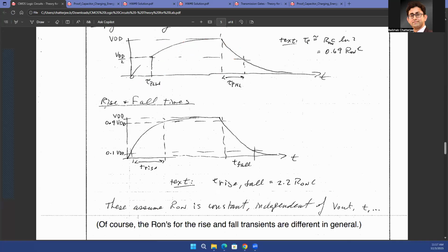So basically, you'll see that the rise time and the fall time will also be defined in many books as just those 10% to 90% levels. So if you're talking about only the rise time, then you're talking about the 10% to 90%. As you are rising from 10% signal level to 90% signal level, that's what is called the rise time.